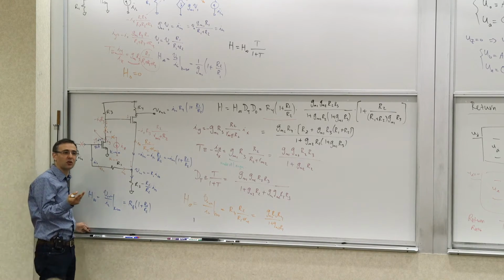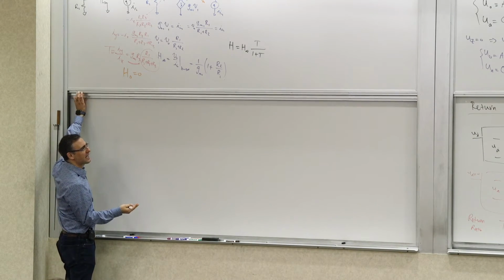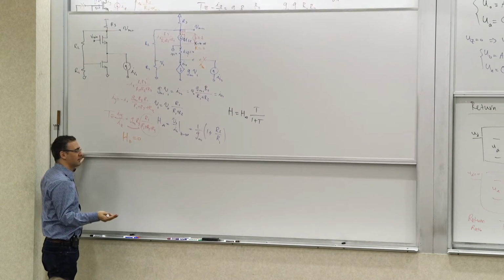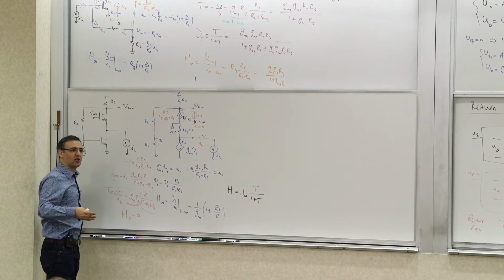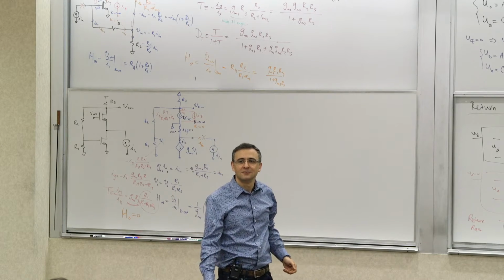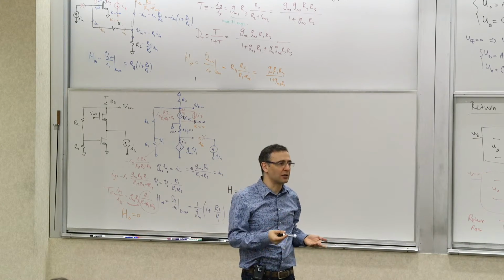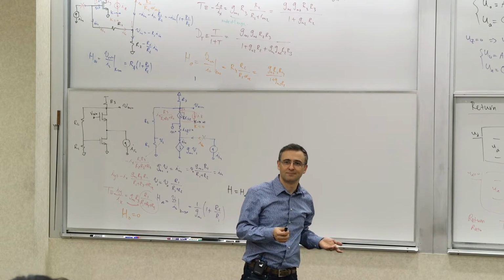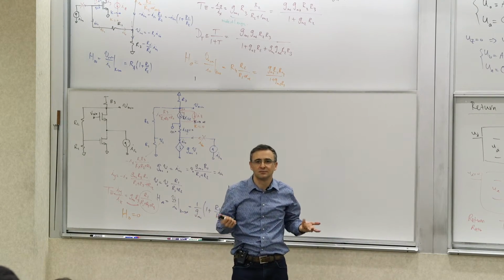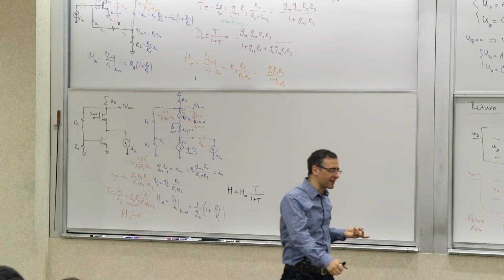An interesting side note. The point is that it's meaningless to say this transistor in general is in a common source or common drain or common gate. You have to say for which input and which output, for which signal, for which calculation. It sounds trivial, but it's something that can throw you off. Okay, so that was another example.